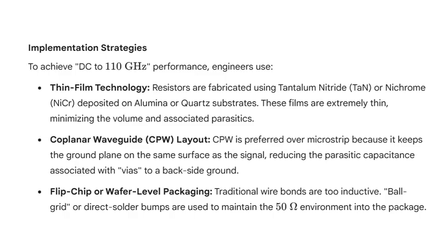Flip chip or wafer level packaging. Traditional wire bonds are too inductive. Ball grid or direct solder bumps are used to maintain the 50 ohm environment into the package.